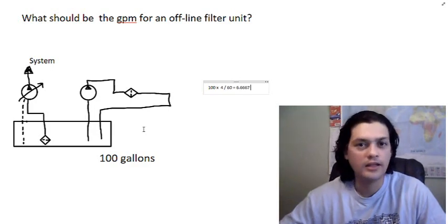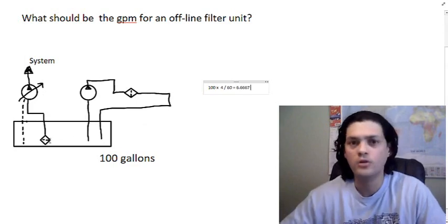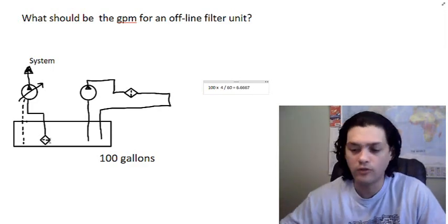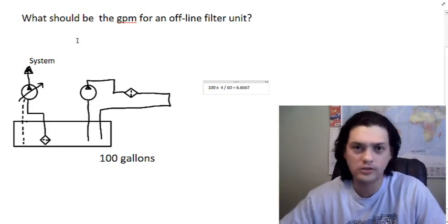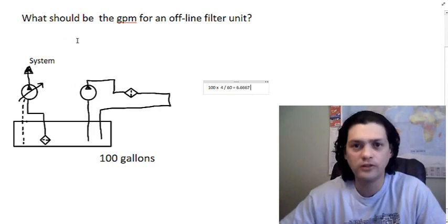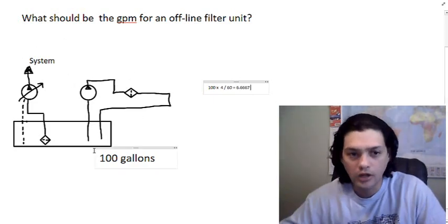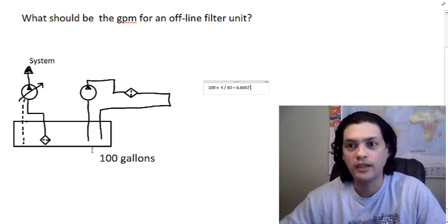Why not? Because in your regular hydraulic system you have, let's say this one over here is a strainer. A strainer doesn't really filter the oil to lower the contamination levels you need in the ISO 4406 solid particle count. Then you have pressure filters and return line filters, and if those filters are not getting the job done to lower your contamination levels, you should put on an offline filtering unit, and you should leave it on the machine at least for as long as the machine is working.